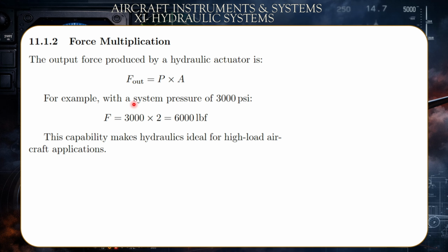Because with a small force and a high pressure, a much higher force would be exerted against the sectional area at the output. By altering the cross-sectional area of the pipe, you can have a larger force at the output since the pressure is constant. So you can vary the cross-sectional area at different locations of the pipe to alter the output force.